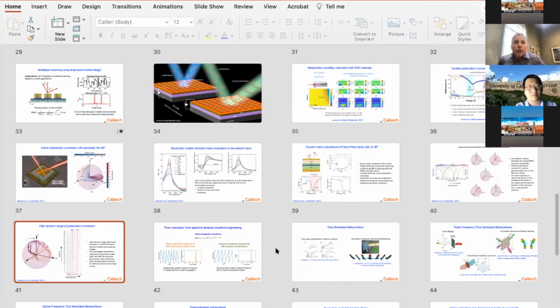I guess there are two ways to think about doing inverse design. There's one way, which is the way I described, which is to use an algorithm and compute it beforehand. There's another way, which is to simply use an imaging detector, which can, for example, detect the profile of your beam, and iteratively optimize in analog fashion the voltages applied in the laboratory to your device until you reach an optimum. That's sort of an empirical way of doing it. But I would say that the computational burden is not overwhelming for this kind of structure.